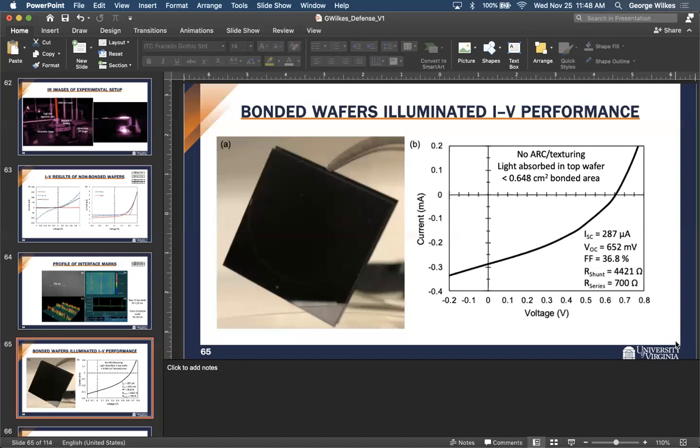Okay, and that would be solved once you bond or cover the surface more completely with your laser. Would you think that solves that issue? It would have more complete bonding area. I think you could definitely get a higher current and hopefully lower series resistance. But as long as I'm using water, it might be difficult to get a really low series resistance because of those Si-O-Si bonds that will form. So we're not talking bulk resistance? You think the resistance only occurs at the interface?